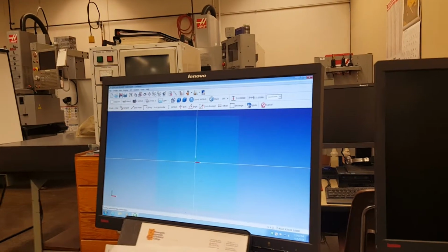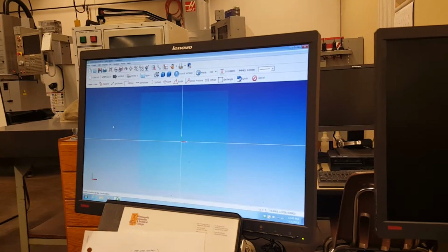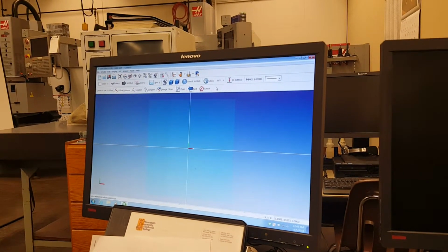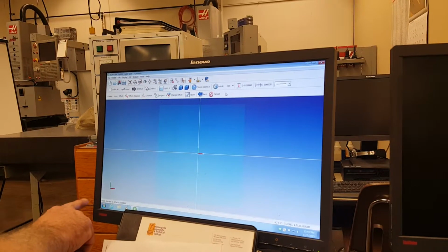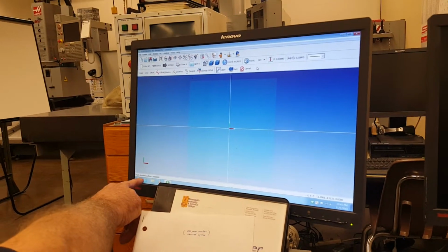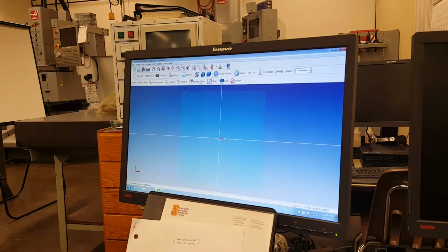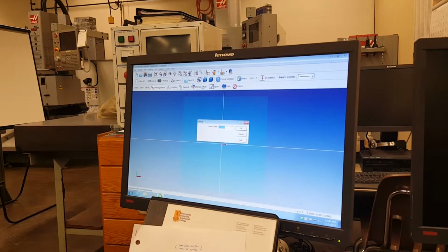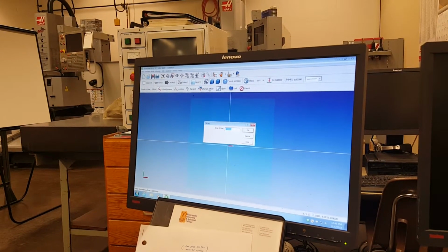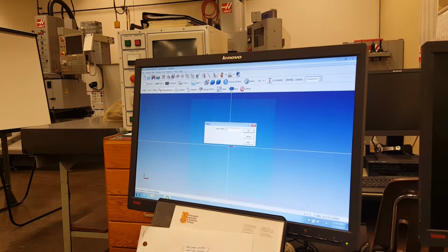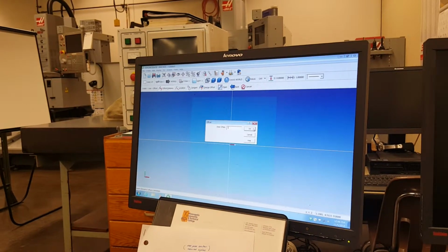So what I'm going to do is go back and create an offset line. And I look down here and it says select element to offset a 1/2 inch. Well, I'm going to change my offset, and I'm going to make the width of the part, or the height of the part I should say, and I'll set 3 and hit OK.